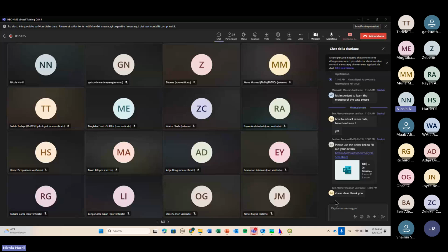So are there any questions? Were you able to perform the pre-process sinks and the pre-process drainage? Because now what we are going to do is to extract the identified stream, to select the breakpoint, so the point at which we want to close our subbasin, and to extract the subbasin automatically. I will give you a couple of minutes.